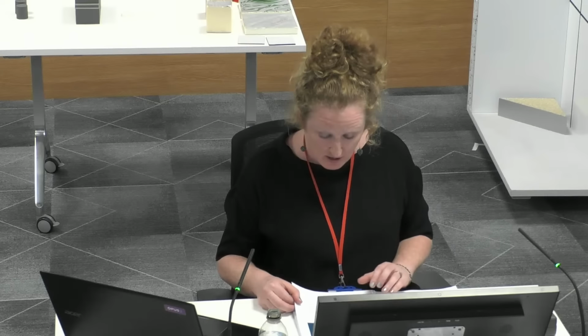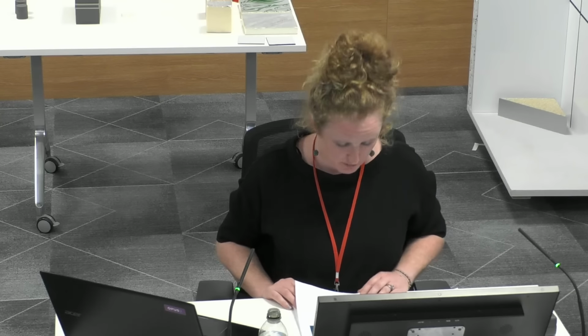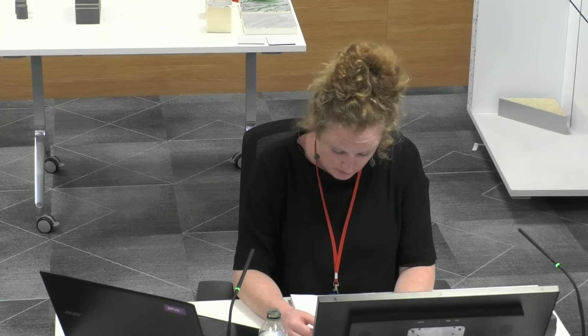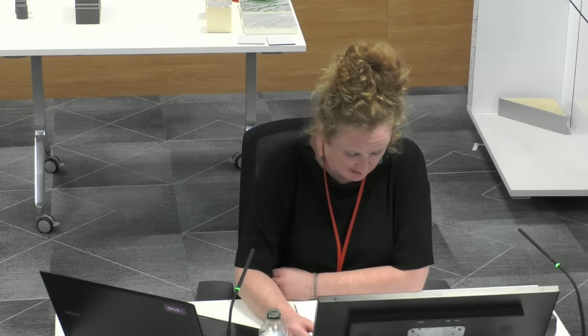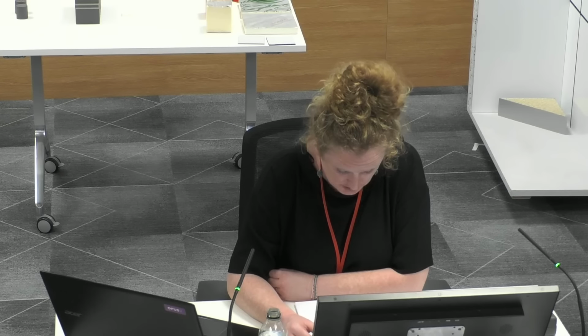Okay, the last section. This is the final section of my presentation, and it focuses on the subject of cladding systems and not individual products as I have dealt with so far. I explain the fire tests for cladding systems referred to within Approved Document B, and these are called British Standard 8414 Parts 1 and 2.